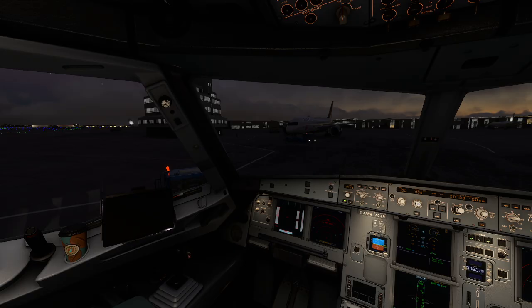I'll check the METAR also, quite good, and I have some wind over here, but that is considerably low, and QNH 994. That is the information I got, and also departure runways 27 left and 27 right. That is what I got from the ATIS, and let's stick to that and plan my next destination.